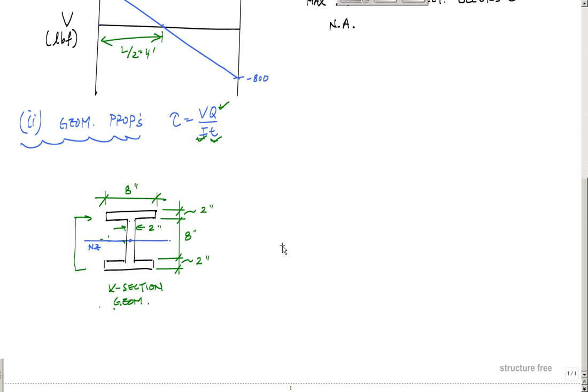But here, if I look at this over here, this neutral axis of the whole thing is just, I can look at, instead of trying to do parallel axis theorem a quick way, because again, the cross section is symmetric about the neutral axis, and this red square has the same centroid as my voids here. These share the same neutral axis, if you will.